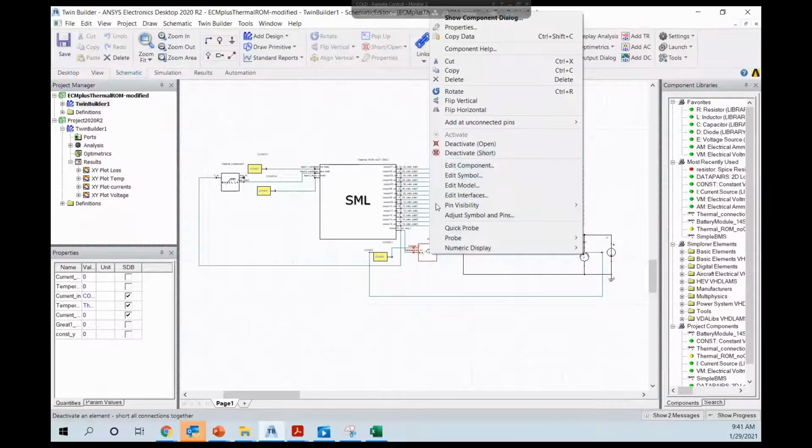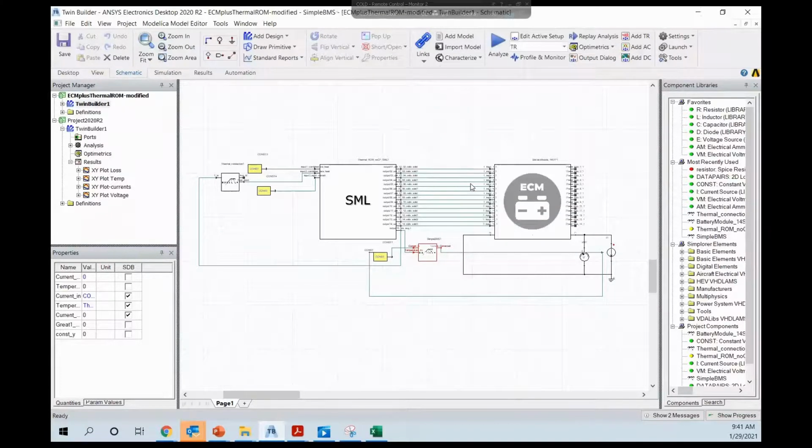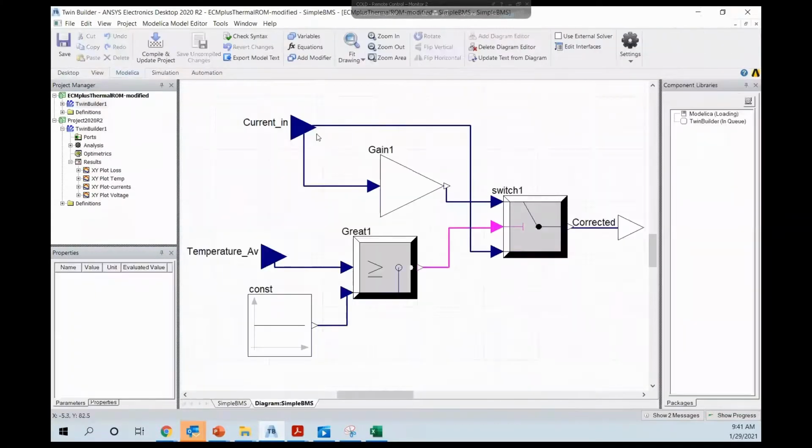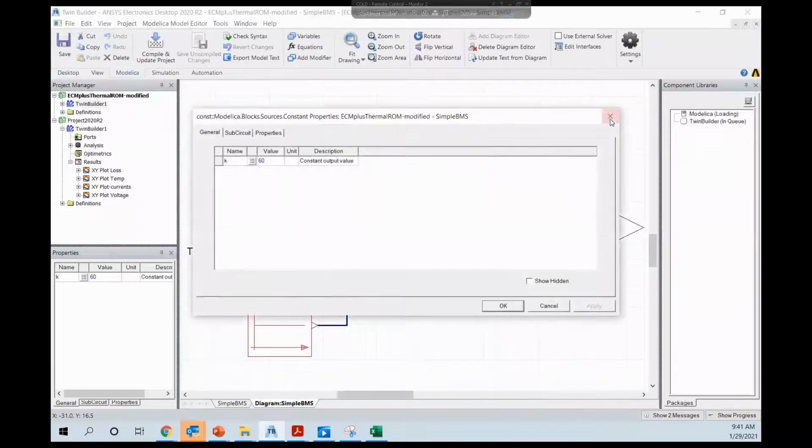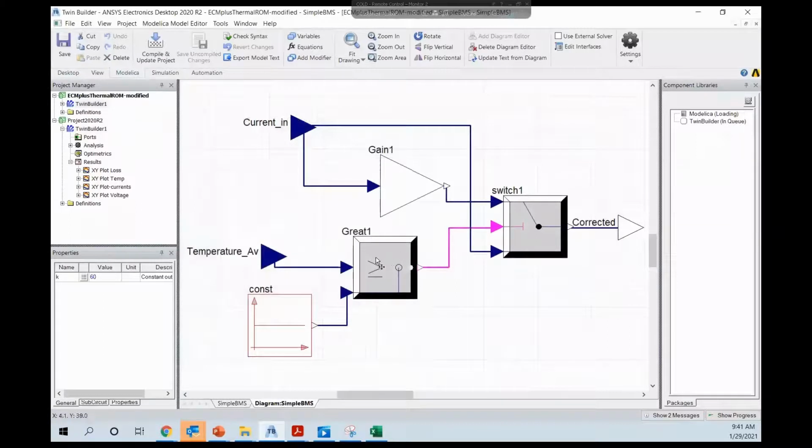If you wanna put, for example, the logic in it, this is what I showed you in the slide. So you can put any value in it. What's the temperature? Like 60 C, and then this is the logic you have, and then you have a lot of components you can add here to put any control mechanism inside this block. And then when you're done with it, you just compile it, and then it gives you a code so you can put in your model.